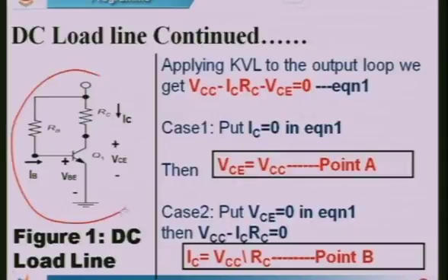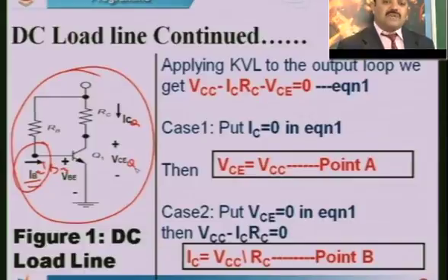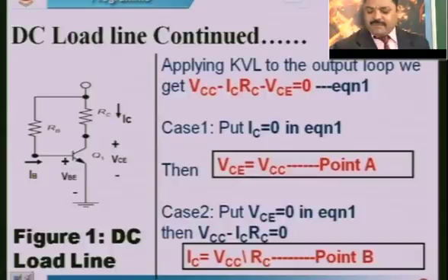So, this is the circuit we have considered. At the input, I have written IB here. Which IB must we apply here? It is IB3 we have to apply. When we apply IB3 at the input side, at the output circuit we get ICQ and VCEQ. These two, collector current and collector to emitter voltage, must be maintained during the passage of the weak signal which is to be amplified.